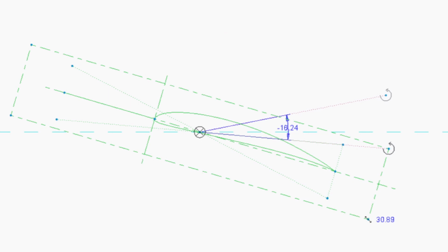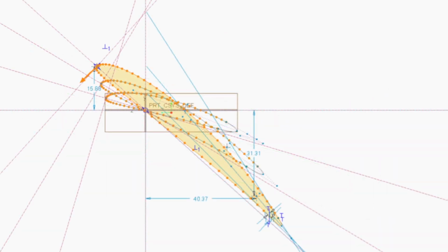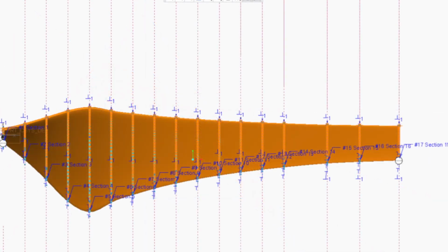I then spoke to Colin Chan, who supervised the CAD modelling of the turbine. As soon as we were set with the aerofoil and design TSR, I began tinkering with PTC Creo to try and figure out which feature was best for replicating a blade. And I found out that the best one to use was a blend function, and blend a few aerofoil profiles together, because the aerofoil cross-section changed in chord length and in angle of attack as we progressed along the blade.